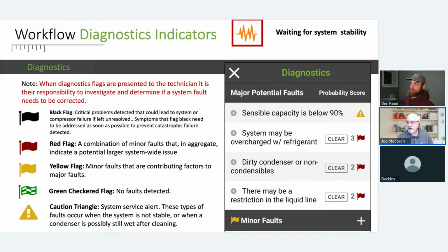So that's the discharge line. It's the same as what we talked about a second ago. There are suction line and liquid line clamps that are required. After that, the discharge line is your additional information. If you use it, we take that information and it's used in the calculations. We don't need it to do an AC system. You do need it to do a heat pump system in heating mode. That's the clarification.